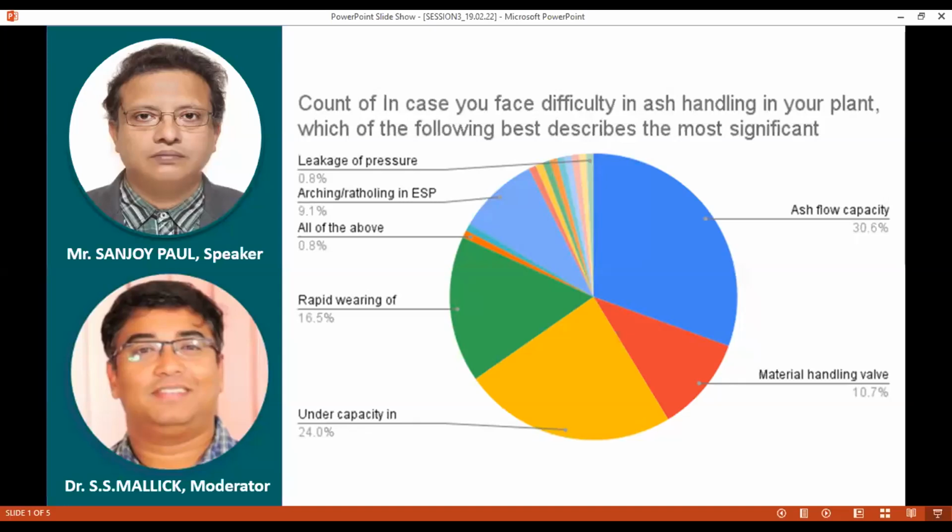The seal is to be replaced at certain intervals of time, and that's why we provide replaceable seals with certain hardness and smooth finish, in both pressure and vacuum lines. So actually the plant user should check whether the seal is being replaced in proper time or not. Preventive maintenance is required.